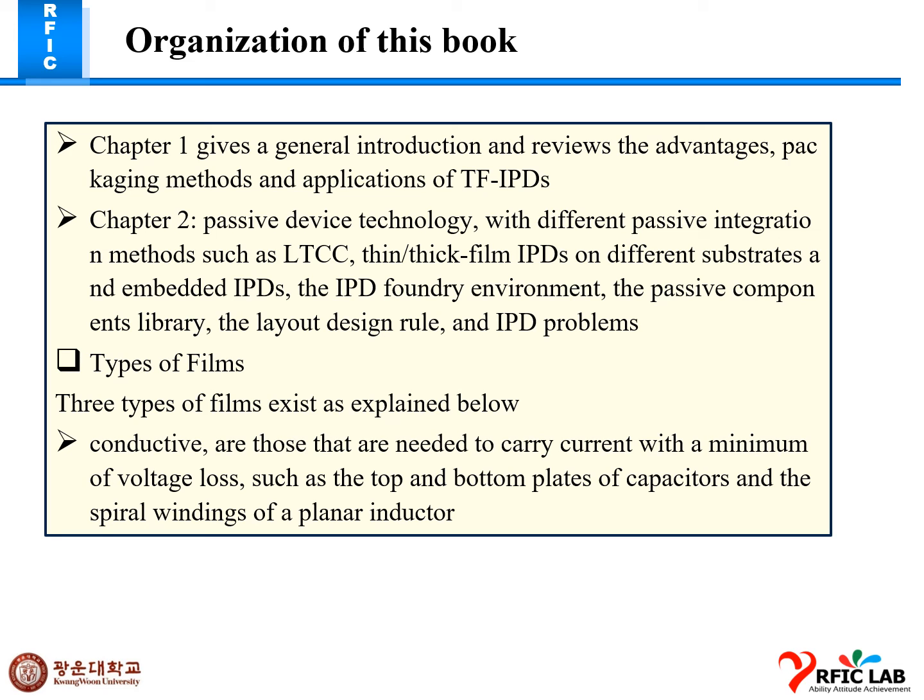Chapter 2 talks about passive device technology with different passive integration methods such as LTCC, thin or thick film IPDs on different substrates, and embedded IPDs, the IPD foundry environment, the passive components library, the layout design rules, and IPD problems.